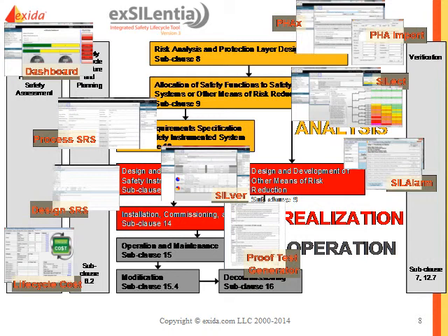Now, IEC 61511 only talks about one SRS, where these requirements are combined, but that means that it's a document that is fluid. You'll have to update it once you've completed your conceptual design. And since in many cases the process hazard analysis and the conceptual design are done by different teams, sometimes it's a contractual document. Updating that contractual document is very painful. So we decided to split it up and focus on the process safety up front, and then the actual design requirements after the conceptual design is completed.